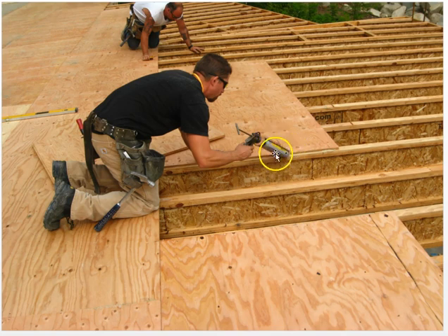So here's a very strong subfloor adhesive that would be put on every joist top, and then the subfloor is laid down and then it is screwed off. So then again, the plans would specify the screws are every foot or so. Sometimes there's a spacing for the perimeter and then a spacing for in the field. Sometimes the perimeter here has to be closer together, and then in the field you have less. And the same goes for drywall.